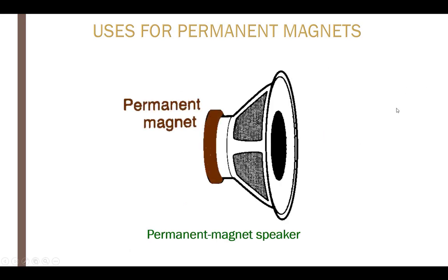A loudspeaker is another example. In a radio, you've got a conductor over here. The waves come in and induce a voltage in that conductor, and so there's my signal. But there are a lot of other stations in there besides the one I want to listen to. So that's where you get into tuning or filtering, another circuit downstream from the antenna. I'm going to filter out all the ones that I don't want, plus any noise that came from sunspots or ignition systems in cars or whatever, and be left only with the particular radio station I want to hear.